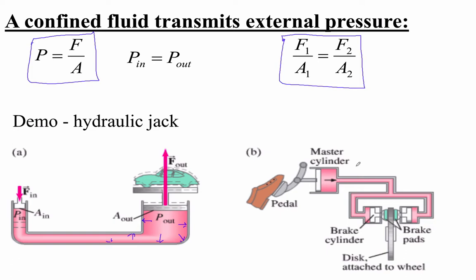Okay. This is a diagram of what happens in the brakes. This is called the master cylinder, right? By the way, these cylinders used to be called slave cylinders. Thankfully, they're not calling them slave cylinders. Okay, but so the master cylinder creates a pressure in this hydraulic system, and then that pushes on the brake pads. This is called the caliper, right? This is the rotor of the disc brakes, right? Let's do a problem here.